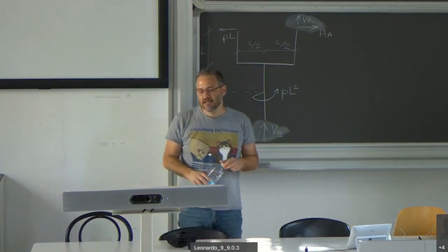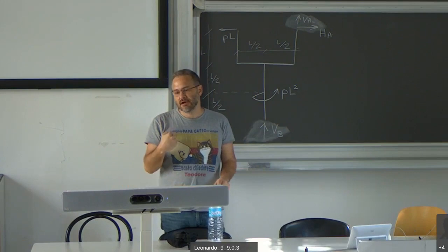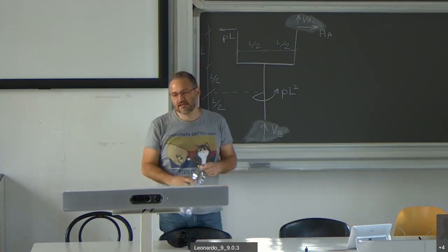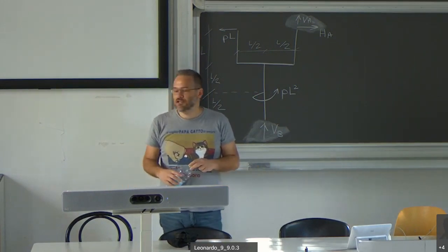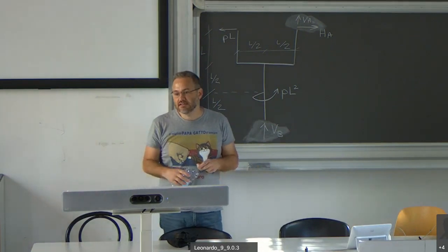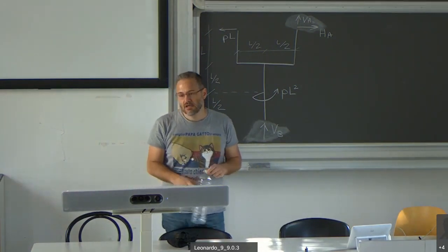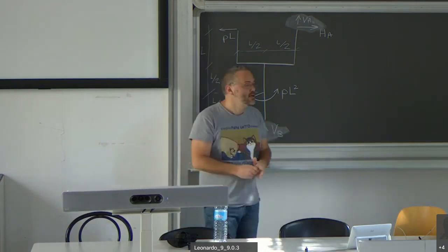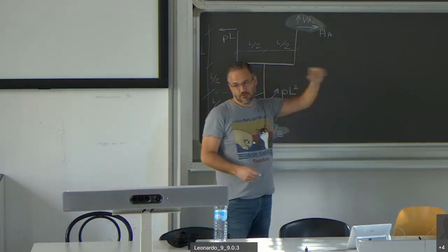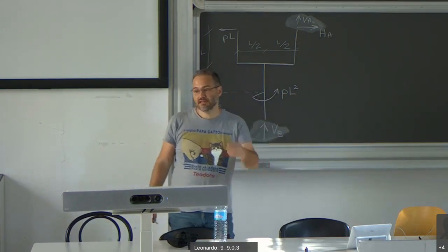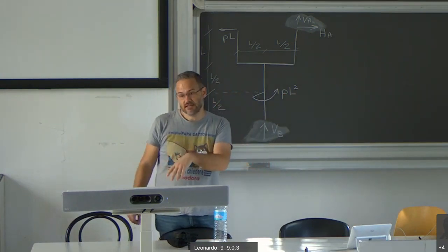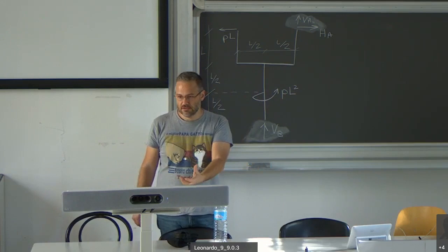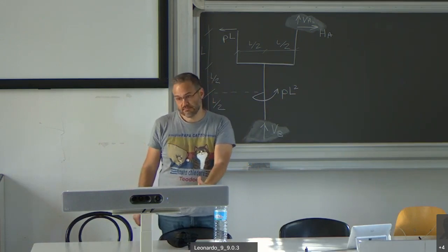Yes. The direction you decide a priori, as Rima pointed out, is totally irrelevant in the sense that you assume a certain direction, which means by pointing this arrow to the right, I assume that HA is directed to the right. I solve with equilibrium equations.